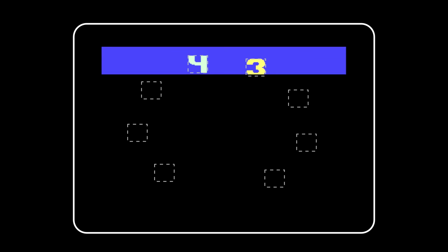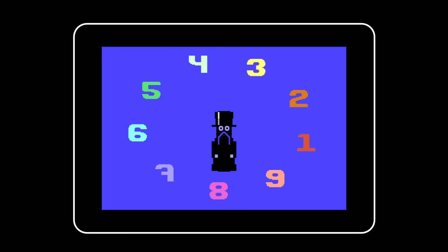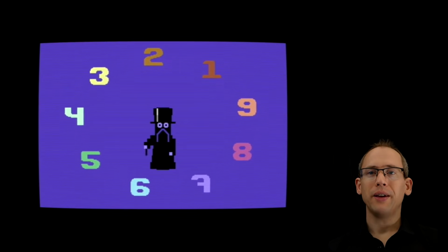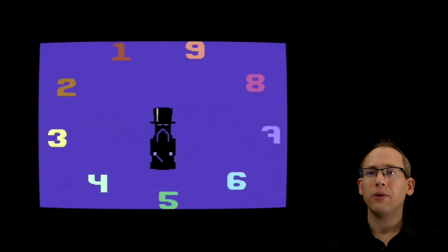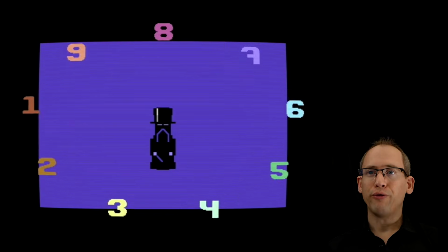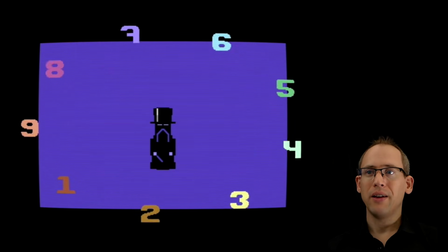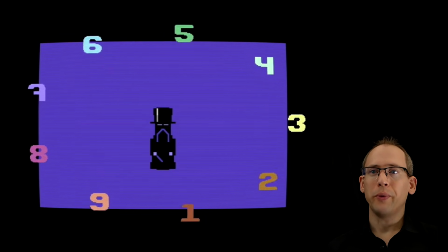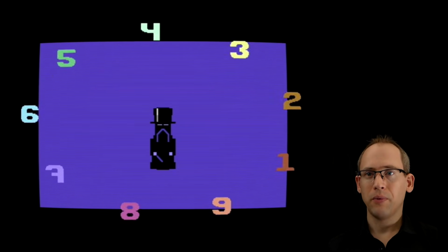In this case, I start by telling the hardware to display all digits except the one at the very bottom of the circle. And then I make the CPU wait until the video chip has finished rendering the topmost digit. At that moment, I reprogram the registers for that hardware sprite to render the remaining digits. But now something interesting happens. The sprites are moving into the border area, but they go in front of the border instead of behind it. This means the border must have been opened using the hack I mentioned earlier.